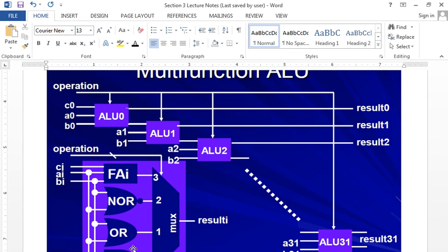If you're thinking, okay, I want to build an efficient ALU with an adder, we've got an adder, we've done the 2-bit adder, the 4-bit adder, the 8-bit adder, the 16-bit adder, right? And you calculate all this out. What you can then do is you have the 32-bit values, right? So then you can start saying, well, a 32-bit value for a full adder, a 32-bit value for NOR, which is just A NOR B for all of the bits.